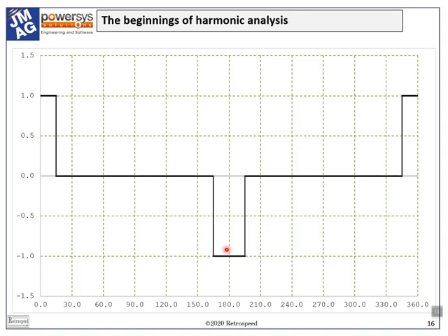In this discussion, it simplifies matters quite a lot to consider pairs of coils, opposite coils with equal ampere turns, because this eliminates even order harmonics and even a homopolar component that would arise if we considered one coil by itself. Now what we do is to resolve this periodic function into its harmonic components by Fourier series analysis.